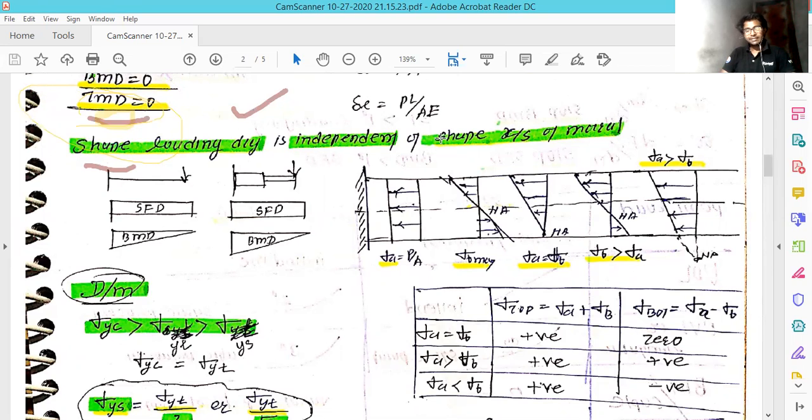And in the second condition, when the axial stress is higher, as you can see in the last diagram on that bar, at the top section it is positive, and in the bottom section it is also positive, and the neutral axis lies outside of that cross section.